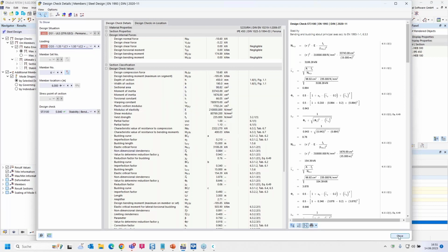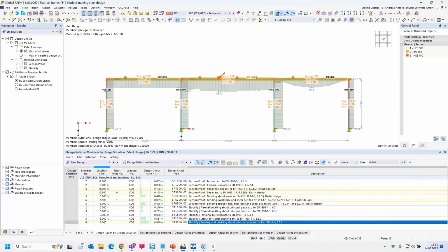Okay, I can leave the dialog. Yeah, this was the classic structural component method, method C, without imperfections, but with effective member lengths. And now we want to examine the model using the approach of global imperfections and the structural component design, which means method B. To do this, we change the buckling length coefficients of the supports back to 1.